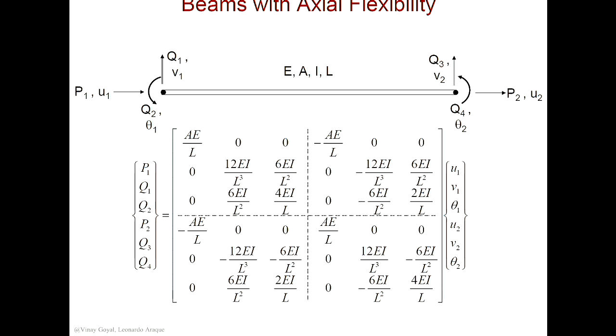A simple example. Take two metals, one very weak and one very strong. What do you think will happen when I stretch that bimaterial part? It should have some bending because it's not purely symmetric, right? There's some difference in there. Okay? Yeah? In modulus, there's a difference, right? And thickness. So maybe I'll get some bending. Okay? But in this case, we're assuming everything is isotropic.